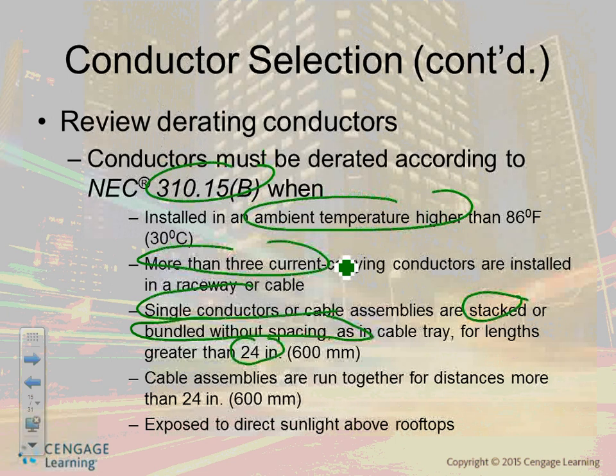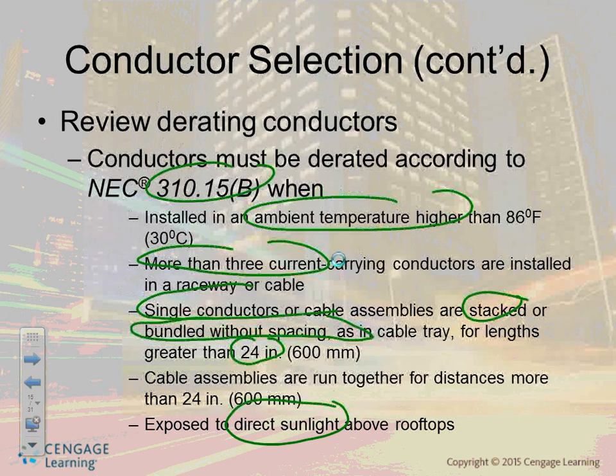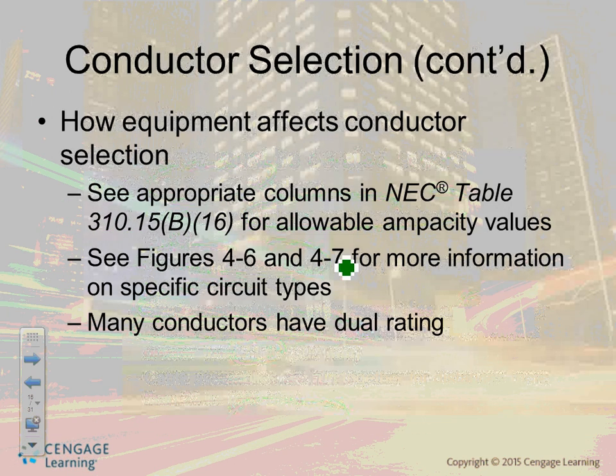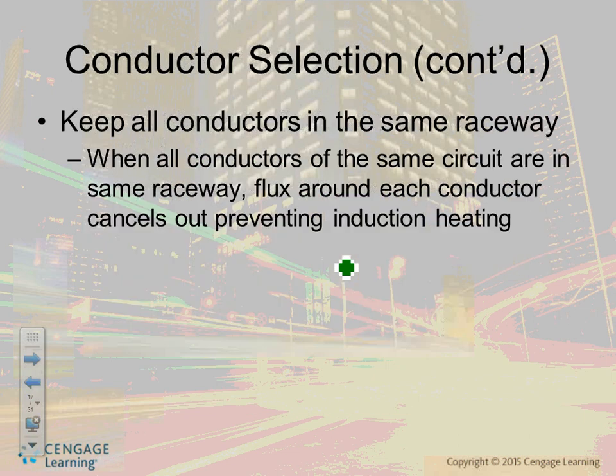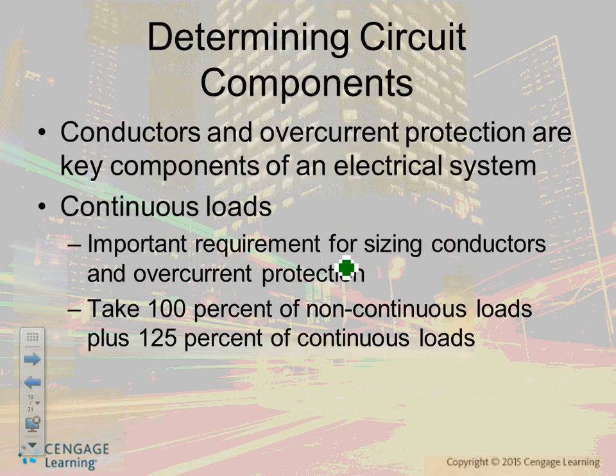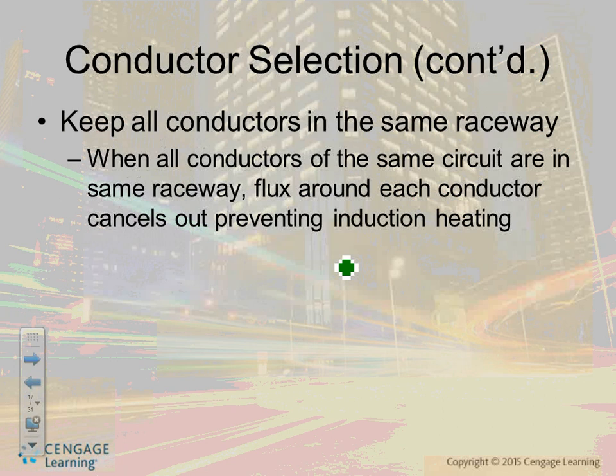And there's exposure to the sun also, that will get you. I'll show you a couple of pictures that are really interesting. Conductors, keep all conductors together. I'll show you the derating, guys. One more thing I want you to take into consideration: keep all conductors together. This is very, very important.